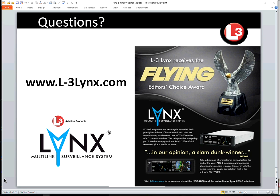And then when you go to the ADS-B traffic with all the enhancements that come with that, and the symbology and everything, the vectors that go along with that, that's on Aspen and shortly will be on Avidyne. Is that correct? Correct. So some of that extra information would not be able to be displayed on some of those legacy displays. However, Aspen and shortly Avidyne will be displaying that ADS-B target with the extra information like your trending information for heading and speed, etc.